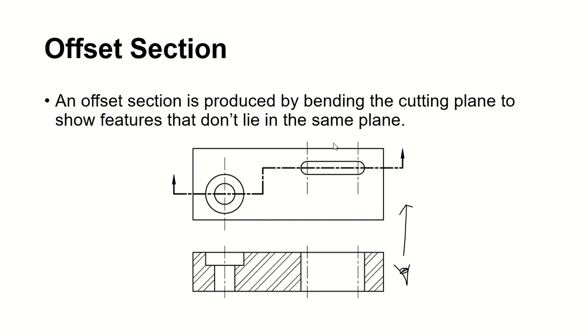After cutting, you lift it up so you can see this. So anyway, here is your arc center. We still show this. Since this is a center line, it has to extend out of the object. Another center here, you're going to extend it out of the object. Don't forget that. All right.